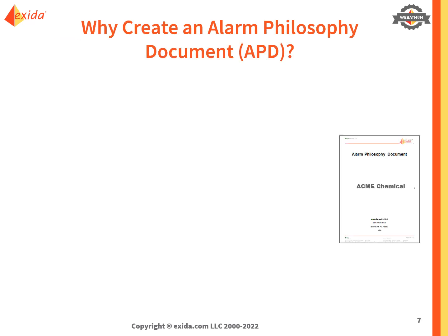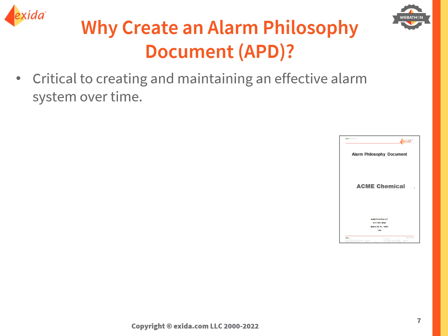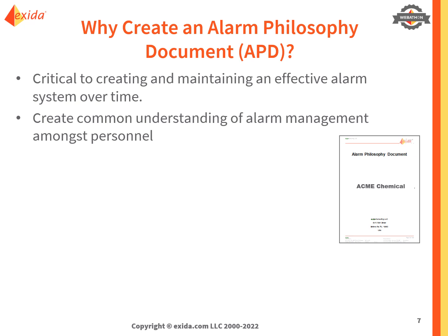But why would you create an alarm philosophy document, or an APD? An alarm philosophy document is the bedrock of rationalization. If you get this right, then you're likely to make a good start with the master alarm database. It's critical to creating and maintaining effective alarm systems. It creates a common understanding for everybody.